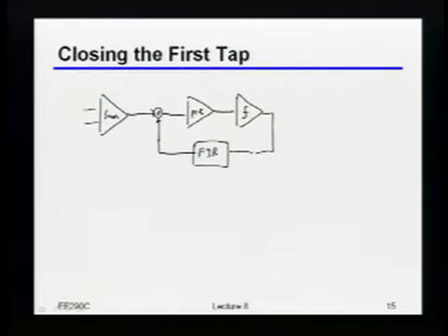Okay. So for that very first tap, things tend to be a bit nasty for the following reason. We've already said that this DFE summer here is self-loaded because of the taps. So in other words, there's this intrinsic speed limit, or really, if I get close to that speed limit, it starts costing me a lot of power to actually do it, right?